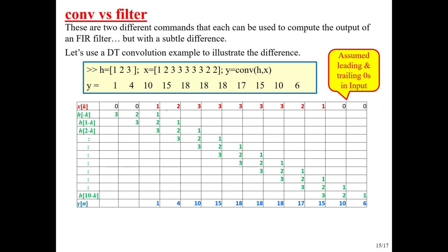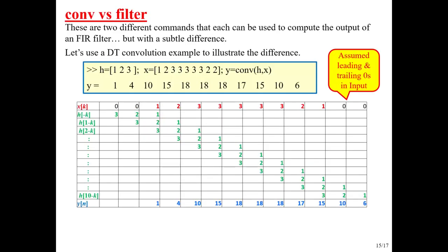So I take the impulse response, flip it, so now it's running backwards, and I align the n equal to 0 positions. Technically I should have zeros out here, but we're not going to show them. In that first position, with just a flip and no shift, that's computing the output at n equal to 0. Look at the products: 0, 1, 0, 0, 0. I only have one non-zero product. I add up all those products and I get 1.